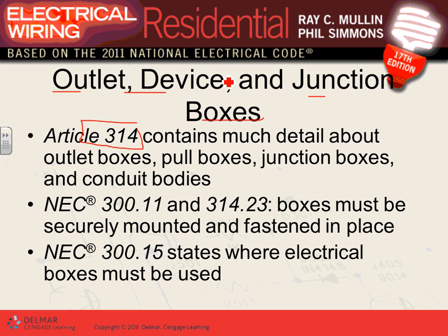The cable, highly unlikely, unless you drill right through the cable, it's not going to arc. The arcing and sparking will happen with the weakest link, which is what? The connection. So that connection could create a fire. If the fire is inside the box, it will be contained and it will not spread and burn your building. That's the whole idea of having all your connections in a box.